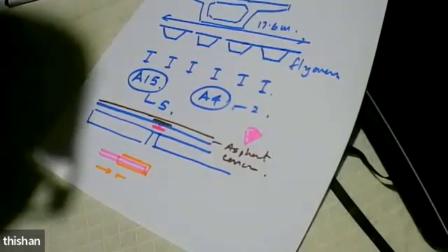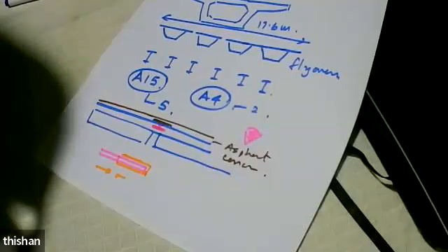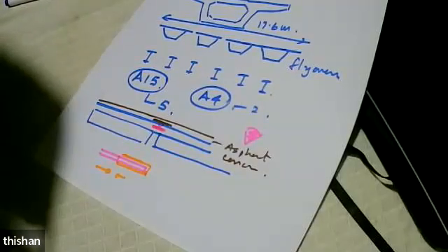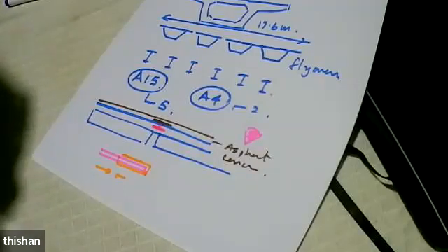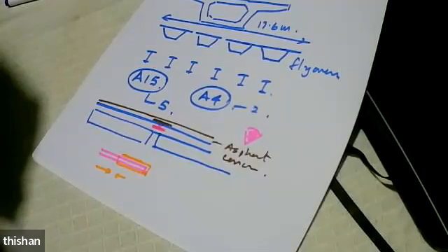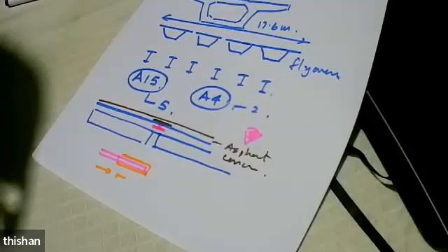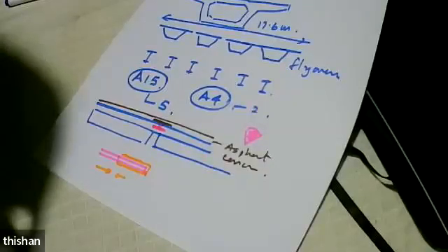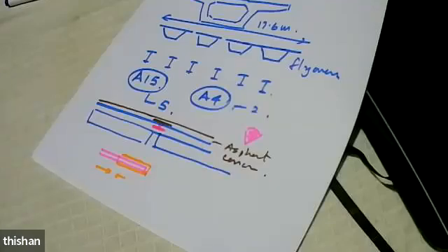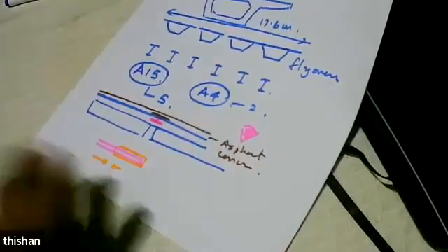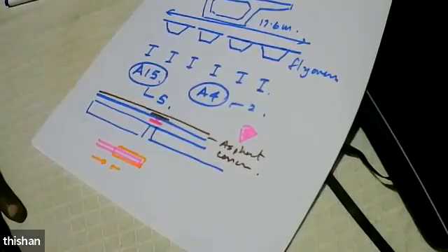Actually, if you do the calculations for Sri Lanka, you will find expansion joints are anyway not necessary, because our thermal movements, the diurnal change in temperature, that is the daily temperature change, is very small. So because of that reason, even if you don't provide any expansion joint, in Sri Lanka, bridges cannot have any problem, especially the concrete. It's not the steel. The steel bridges can have problems, but concrete bridges will not have any problem. So that is the normal situation. So anyway, these have worked well.